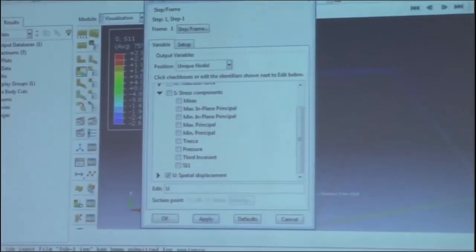So we have one element per truss, and that element has an integration point somewhere. Is it usually the geometric center? For truss, it's the geometric center, yes. Later, I think in chapter 7 or chapter 8, you will learn the location of the integration point for different geometries. And this is one way to check the result.